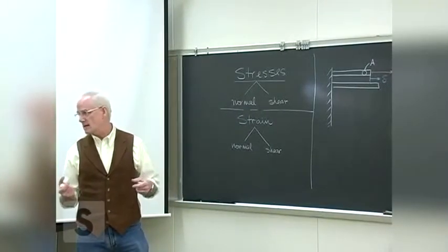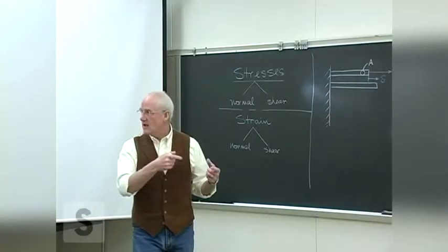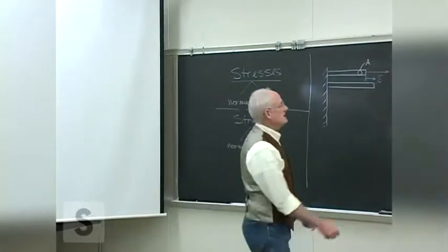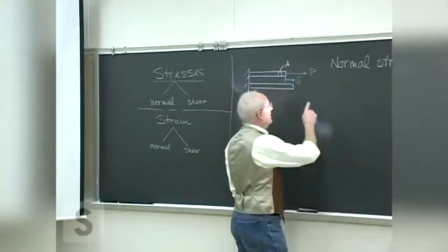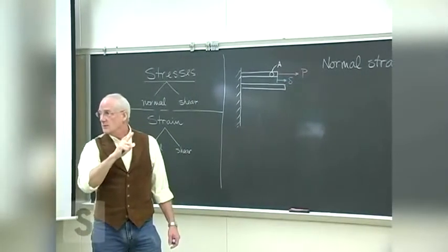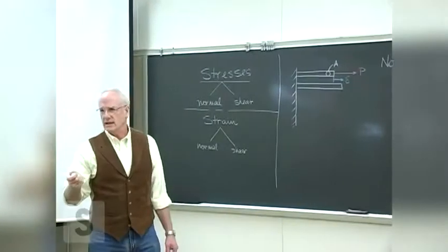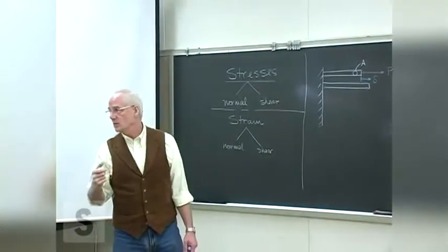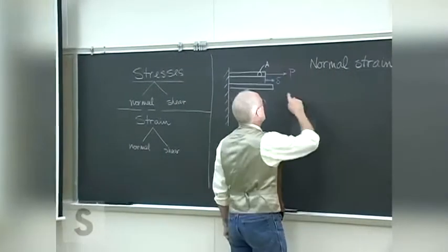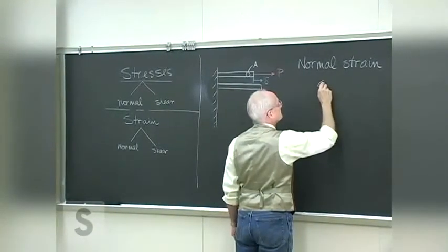If you don't deform them past a certain limit, then when you release the load, they will return to their original size. Of course, you can imagine with steel and the like, this deformation is very, very small, but with certain other structural materials like rubber, which can be used in certain structural situations, as we'll see, this deformation is large enough to even be visible.